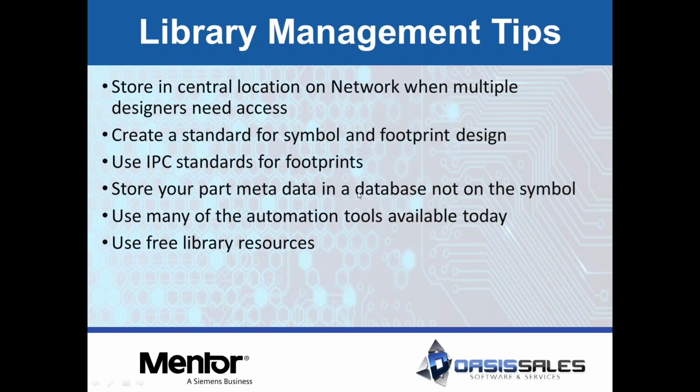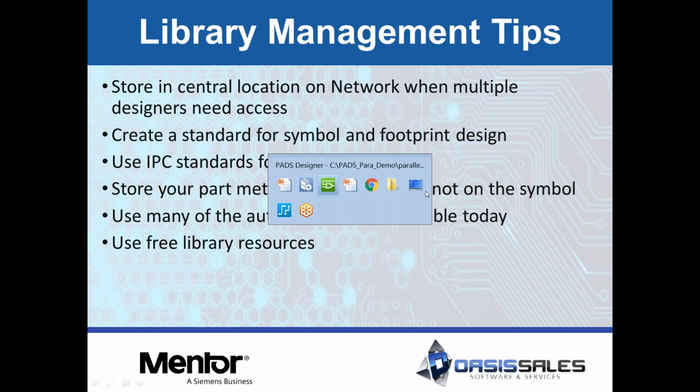Store your part metadata in the database, not on the symbols. Okay, pretty much every tool out there has some type of database tool that you can tie into for your library content to help you find parts, search for components, and pull that information out of a database instead of putting it static on a symbol. Okay, if your tool does not have some type of database access tool, look at some other products out there.